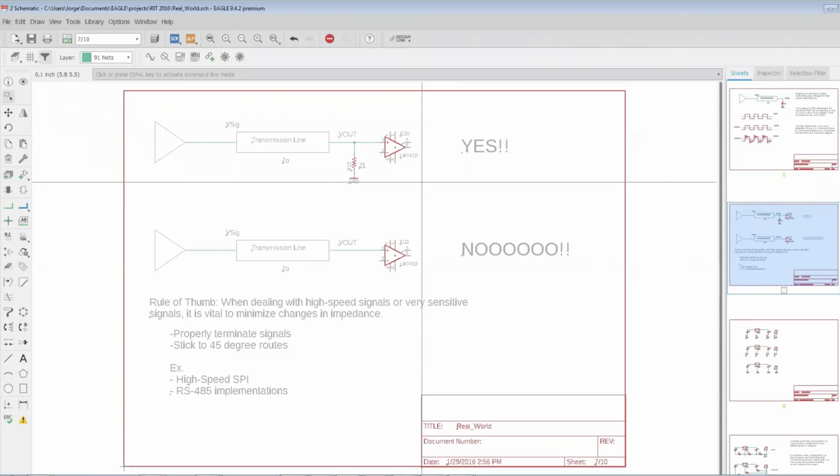So what's the key? Don't think of things in terms of a ground. You really shouldn't ever just think of an infinite current sink. It's a good useful approximation when you're not in the high-speed regime. But think about every trace that goes out of my IC, for example, out of my Arduino: it has to come back to the battery, to the ground.